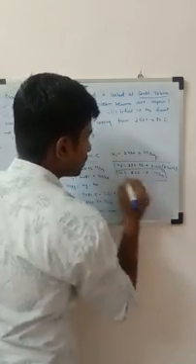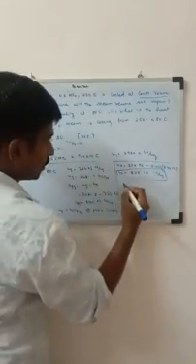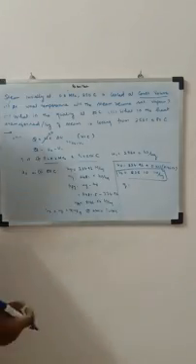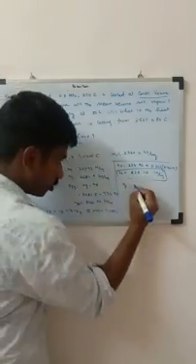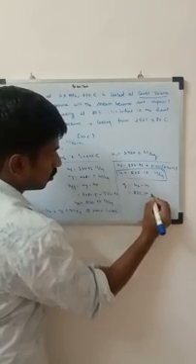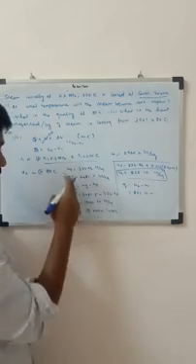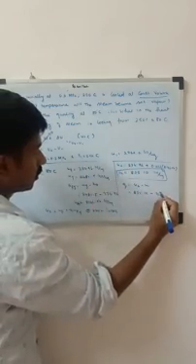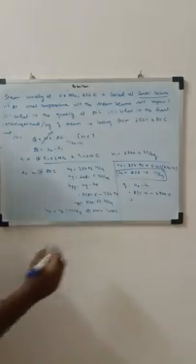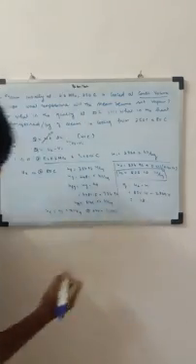And we know that the heat transferred, heat per kg, Q is equal to, per kg means small letter, that's why I use small letter. Q is equal to U2 minus U1. Therefore is equal to 835.10 minus, what is the value here? This is about 2729.0, which gives me a value of minus 1890.9.